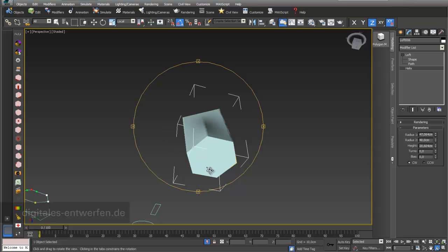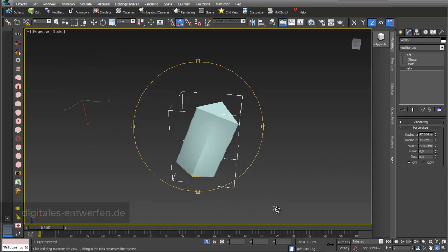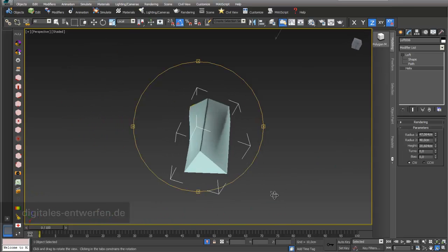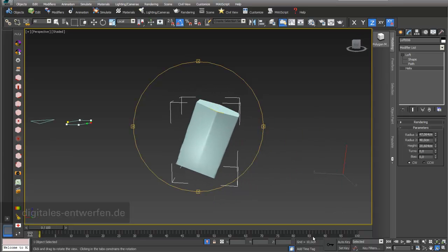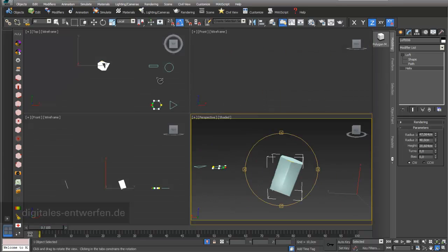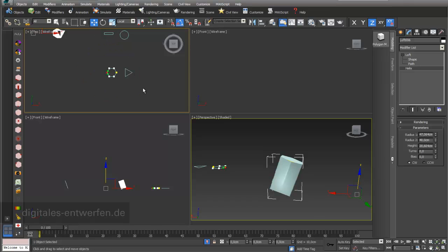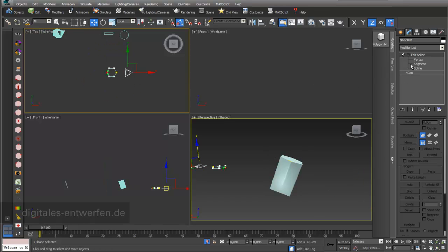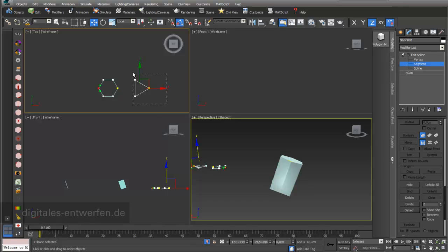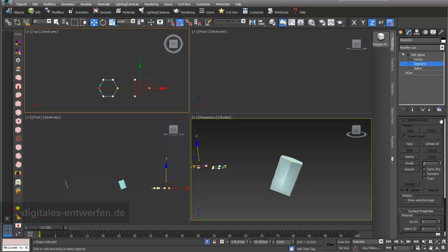We just want to see what it looks like if I just have the same amount of vertex points in my triangle. Okay, I choose my triangle, and it is an instance. So what I can do is I can just go into segments. I select all segments, and there's one function under geometry in edit spline.